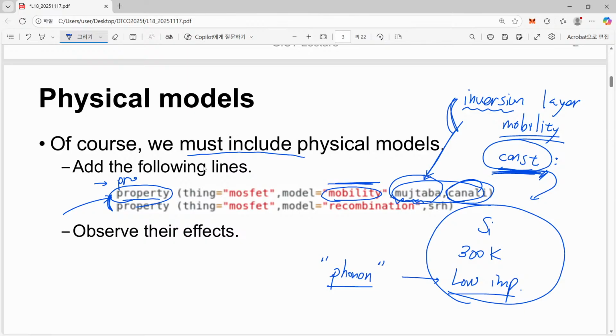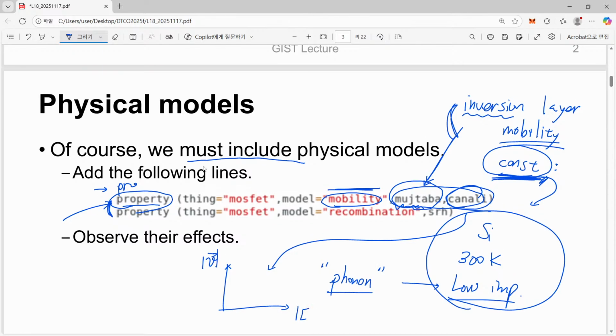And measured in this case, velocity, electron and hole velocity as a function of electric field, but this electric field is lateral electric field, meaning the electric field applied in the direction of electronic motion. So if we have an electron, let's assume that this electron is moving in this way. Right now, our lateral electric field is the electric field heading in this direction. Please don't bother with this negative or positive sign.